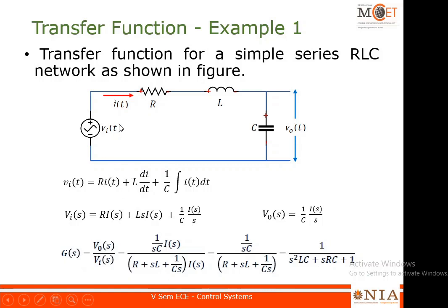So I think we have followed all the steps. We have taken the system. We have written an expression which is governing the operation of this system. We have taken the Laplace on the differential equation, and then we have appropriately taken the output variable in the numerator and the input variable in the denominator, so that you get the transfer function. The transfer function is now given the name G of S.